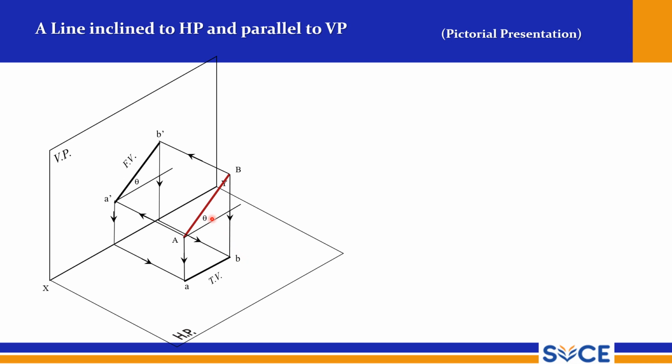When theta is equal to 90 degrees, students, then you can see a point only. So the length from 0 degree to 90 degree becomes reduced, from actual length to 0. So that is the significance of theta angle, and the corresponding top view will have the reduced length. So please remember the word apparent length.